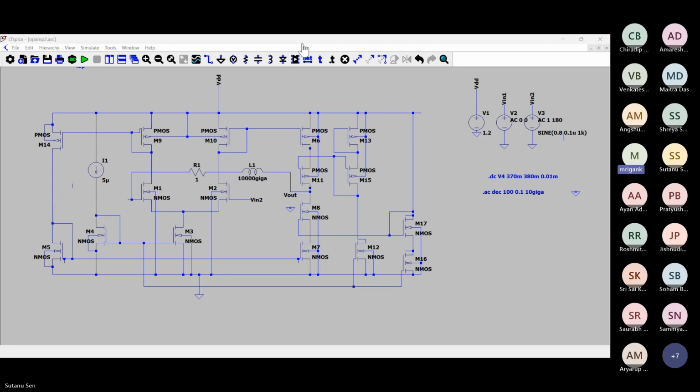So how much gain to have? It depends upon many things. It depends upon the target precision. If you want very high precision gain in the amplifier, you remember that if you make a feedback amplifier, the open loop gain plays a role, right? The ideal gain is just given by 1 upon beta in the feedback amplifier, but it has a factor of A naught beta divided by 1 plus A naught beta.